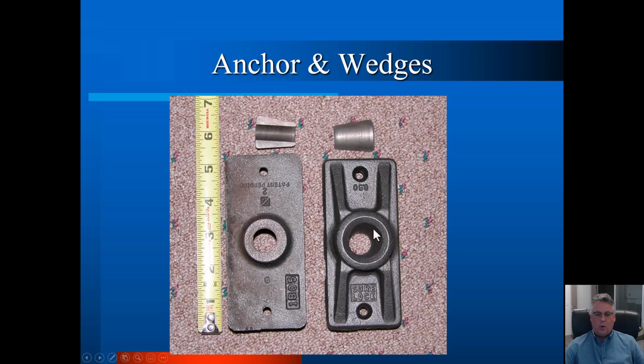This is a tapered hole. The tendon, the strand, will come through. I use the term strand and tendon interchangeably. It's not really correct. The strand is just the steel. It's just the 7 wires that are intertwined to create that strand. The term tendon is actually the entire system of strand, grease, plastic sheathing, anchors, encapsulation. It's the full Monty, but I think all of us tend to just use those two terms interchangeably, and I apologize because I will do the same thing.